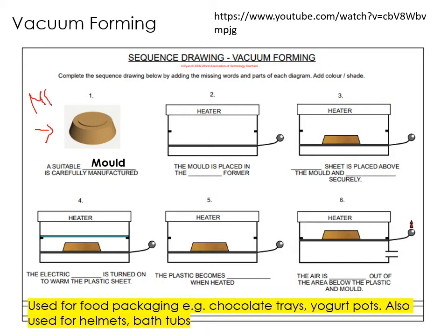You're going to have to bear with me a little bit with my writing. Something like MDF or styrofoam. That is terrible, but you get the idea. And also it has this thing called a draft angle. The edges of the mold are angled. Oh, I've even got it on there. There we go. They're angled because it means that the mold can be easily removed. So no undercuts, that's also important. So if you can't have the plastic go kind of like in within itself, otherwise you would not be able to remove the mold. So it needs to be a really simple hollow shape.